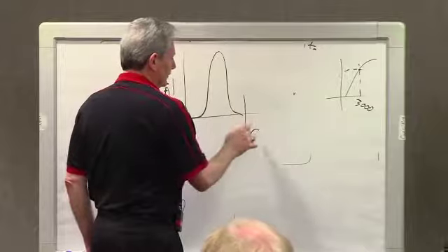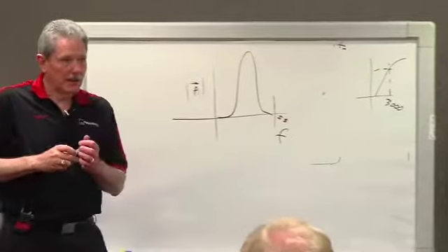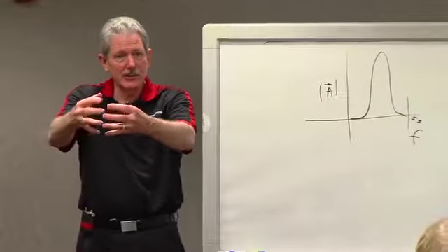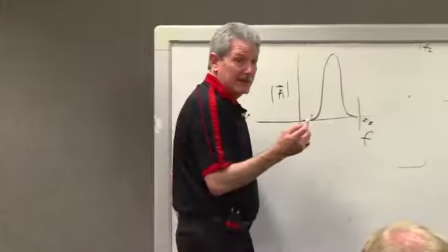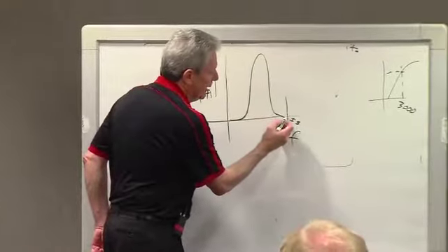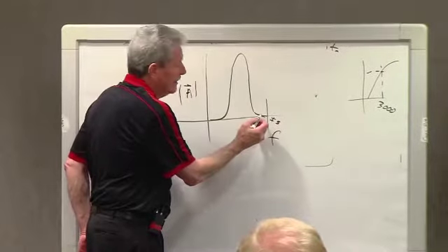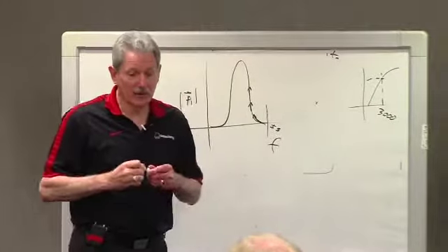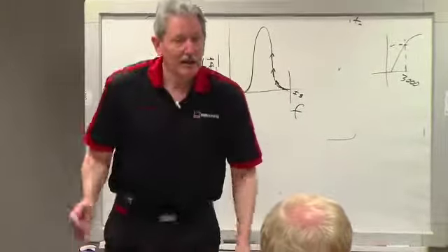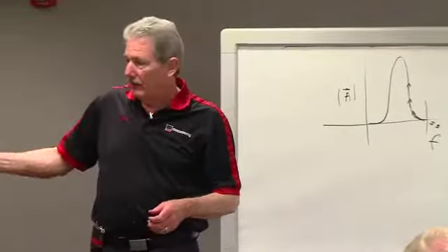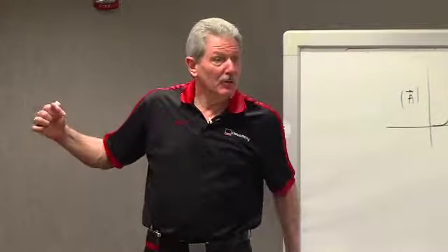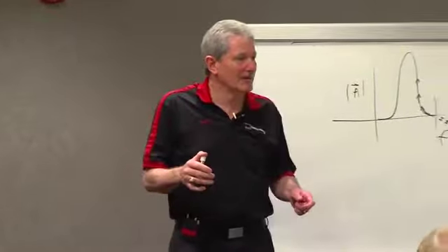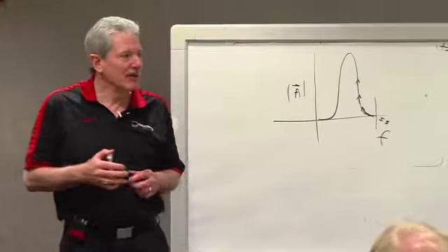Here's the idle speed. As soon as they put a load on, it instantaneously sucks the energy out of the drivetrain, and because it's at idle and there's an underpowered engine, it begins to walk back. The speed begins to decrease, and it starts to walk up this curve. During that time, it's a noticeable shake. This could be manifest with the power door locks. The rear defog was a bad one. The seats, the movement of the seat. All of that caused this objectionable engine shake.